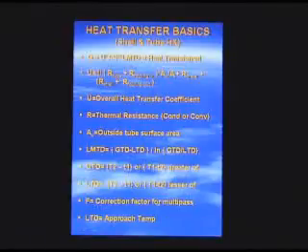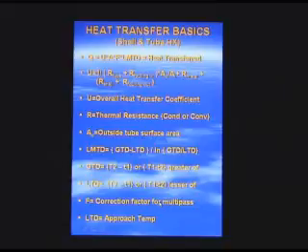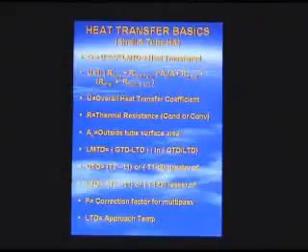The correction factor, if it's pure counterflow, there's no correction factor. If it's a multi-pass exchanger, which we'll cover in a little bit, which shows how that's determined, there's a table in your handout showing that.